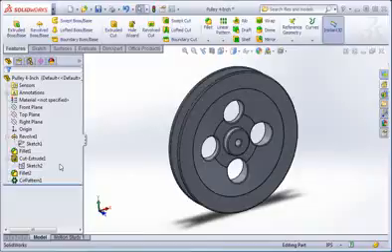So it's easy to see that making a single hole and then using the circular pattern command makes the features easier to edit. Now I'm going to show you how to make the same pattern using the two-dimensional circular pattern command, and then we'll explore editing both methods.